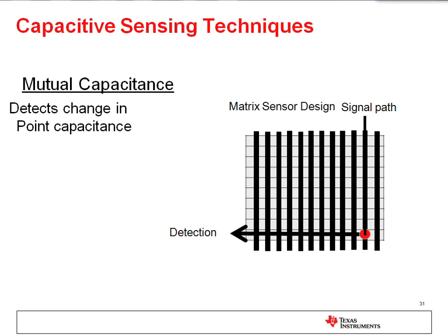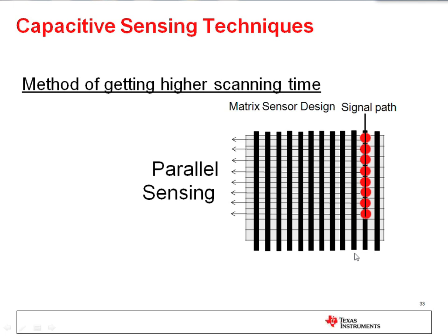So in this case, what we have is one touch point that's detected, and then it's detected here, and then we can see that by driving a row, we can detect, oh, look, there's an actual gesture that's occurring here, and that more data points are being sent to your touchscreen controller to indicate that the gesture is going. However, it is on your controller or applications processor to actually decide if it is a gesture and what should be done.